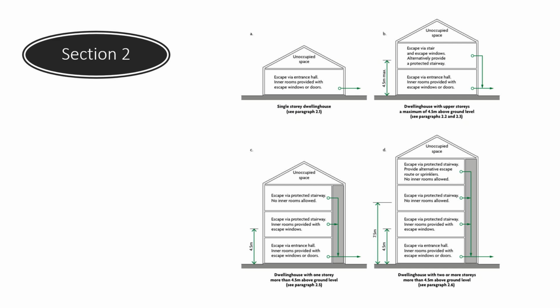That's not the case. So using that diagram on the bottom left-hand side, three-story, we've got 1 story above 4.5 metres in ground level. You need to have a protected stairway. Definition of a protected stairway is FD20 doors installed with fire-resistant enclosures of 30 minutes from top to bottom, circulation spaces. That's it. That's how you comply.